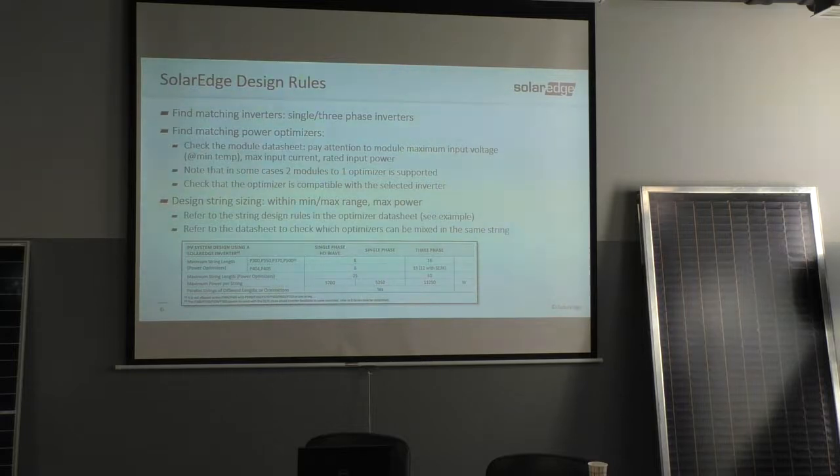So if you have 11,250 watt divided by 400 watt, you will get the maximum number of modules that you can install. It's easier to calculate with 250 watts. If you have 250 watt modules, you can use 245, because 245 multiplied by 250 gives you 11,250.